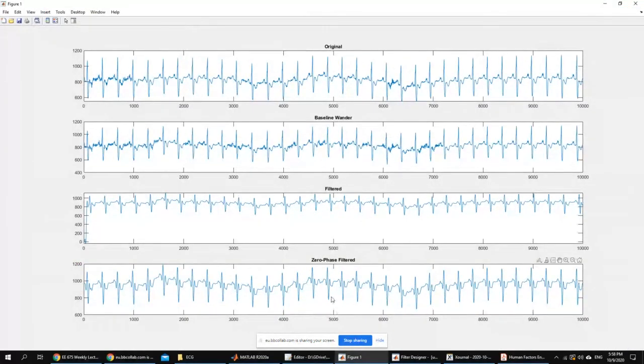Now you started seeing a distortion in the ECG signal itself. So now the ECG doesn't look right. This is not acceptable. So the previous results, basically here you don't see any high frequency noise. You see very clean, very thin lines that basically show you that you don't have any EMG artifact anymore. But having no artifact on a distorted signal is not useful. So you have to have the original signal exactly the same with a reduced artifact.